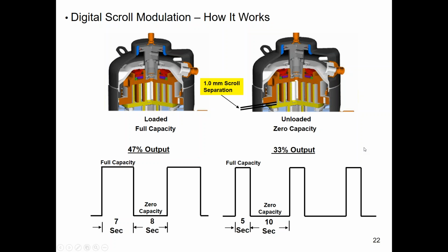Claudine asks, how do you manage oil entrainment on scroll during intervals when the scroll is off? That's a great question. The longest zero capacity or unload period is like 8 seconds. On some units we have 10 seconds, but never really anything longer than 10 seconds off time. It's such a short duration, and then we're back on 100% that it moves the oil along just fine.